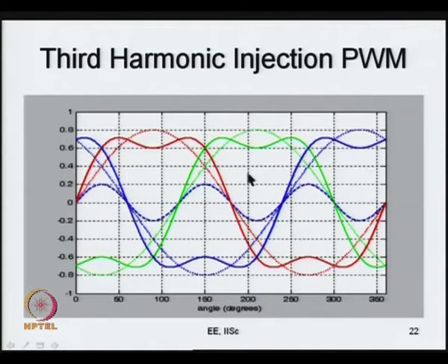is shifted by 120 degrees, but the third harmonic component is unshifted. Because third harmonic is shifted by 120 degrees, it means at the third harmonic frequency, it is simply shifted by 1 cycle time. So, you add the third harmonic to MR and MY and you subtract the two, the third harmonic will vanish, just as the second harmonic vanished there now.